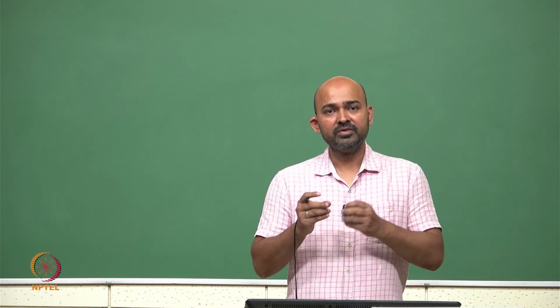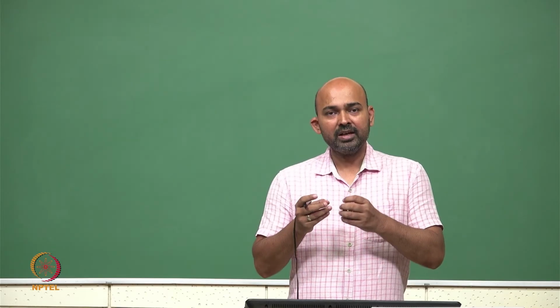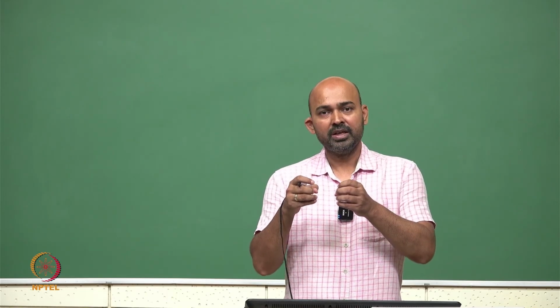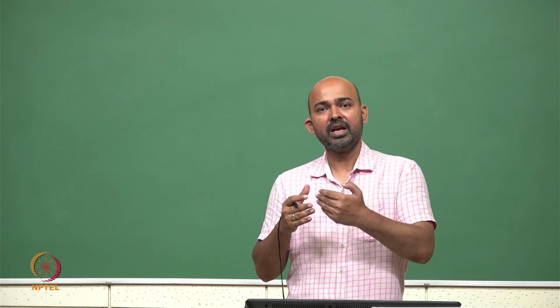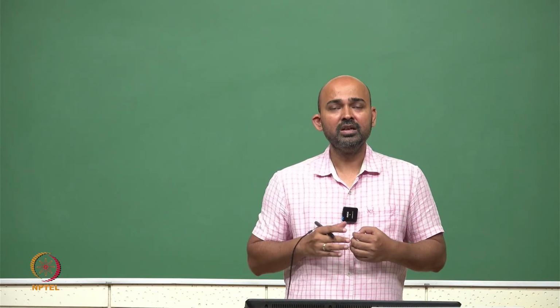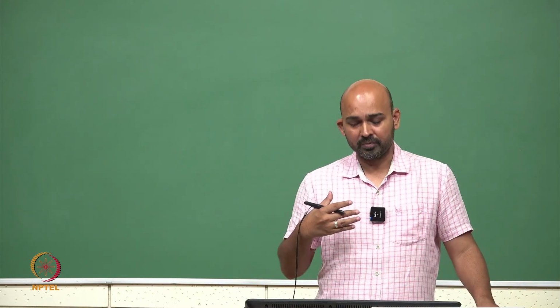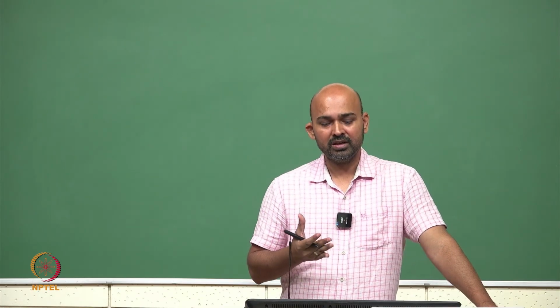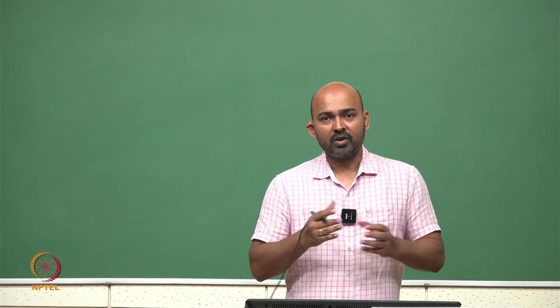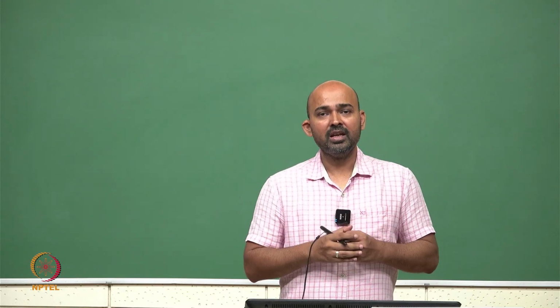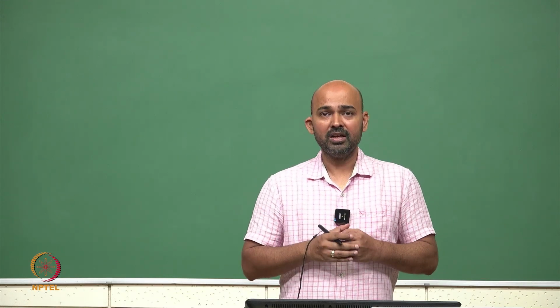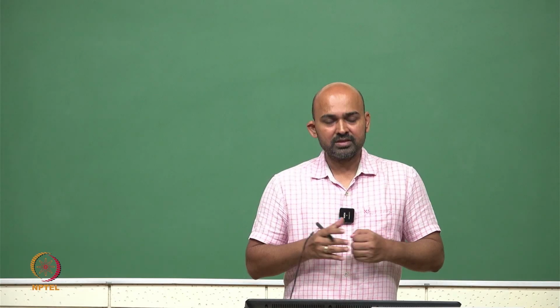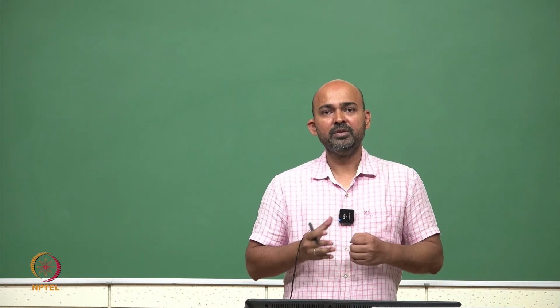As we discussed, these vias or these holes create a boundary of impedance mismatch, and whenever we have impedance mismatch, the signal is going to be reflected from there. So for that reason, we want to have as few vias as possible. So that is a trade off between going to a single layer PCB or a multi-layer PCB. So this is the complete process of PCB fabrication.